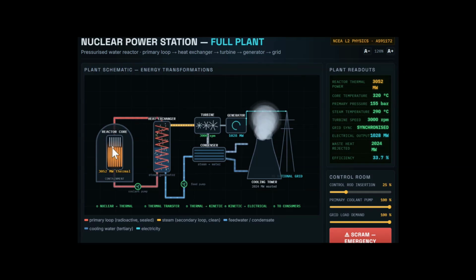This water here is doing two things. It's being spun by the coolant pump. We really want that water to keep going through. It's going to be superheated and then heat up the other water, turn the turbine. We get electricity. Again, it's a really, really delicate operation. And if we have some problem, we can always scram it, the same as we did before. You see the power rods come back in, and even then, it's still not going to die away immediately.